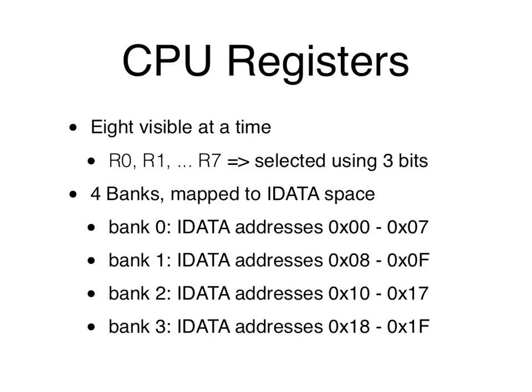Okay? And so you could always get to the data location using the address I talked about. Now, but that takes 8 bits because you're just treating it as memory, right? 256 locations. But if you're using an instruction that refers to a register, then you can pick only 1 out of 8. But which 1 out of 8? Well, it depends on the bank selection. And the bank selection depends on the setting in your processor status word. Okay, and we'll show you some details later.